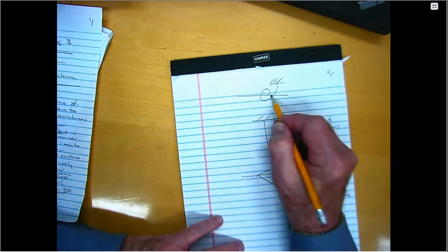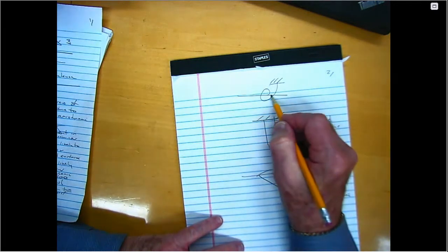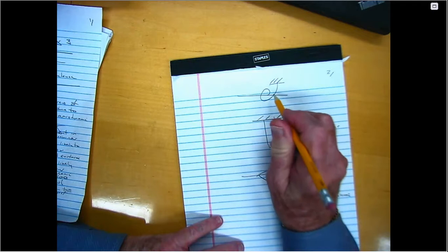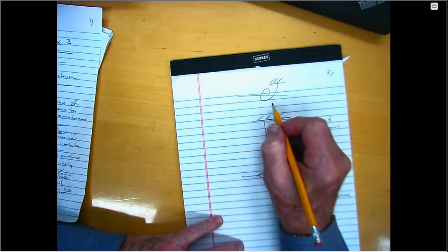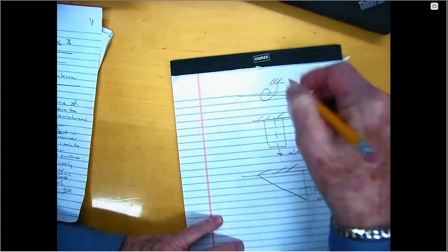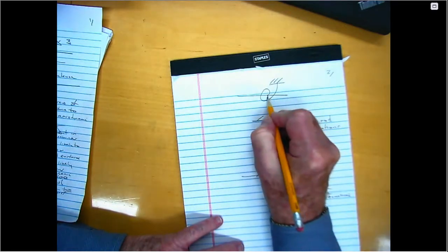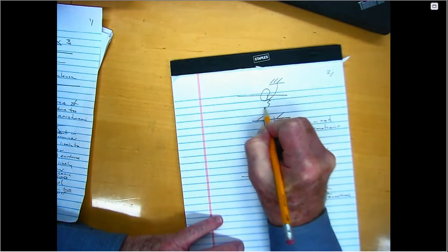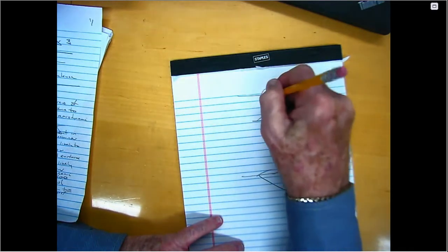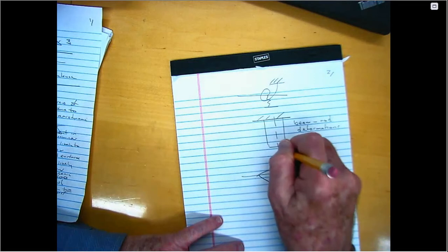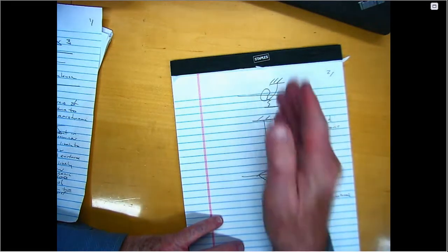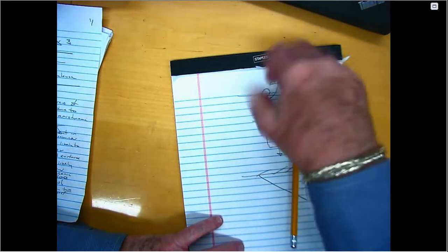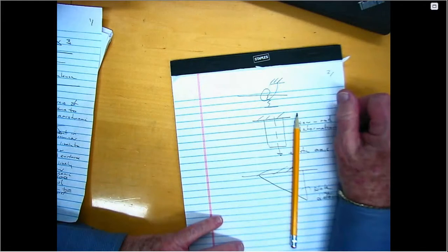And of course, in this case, for coupled mode flutter, this model can exhibit coupled mode flutter, but to do that, we have to have two modes. So we need not only torsion in this model, but we also need translation, or the counterpart of bending of the elastic axis, right? This thing translates up and down on this vertical spring, but it also twists about the elastic axis.